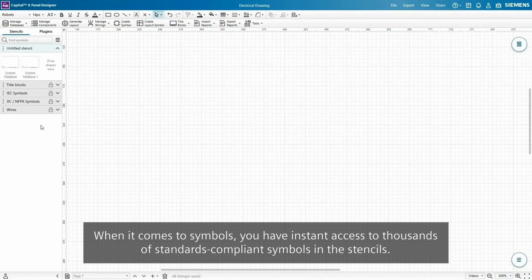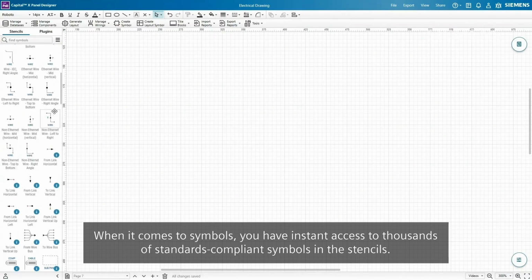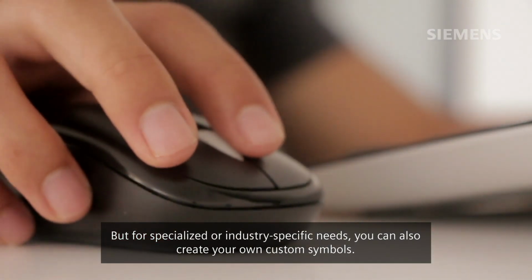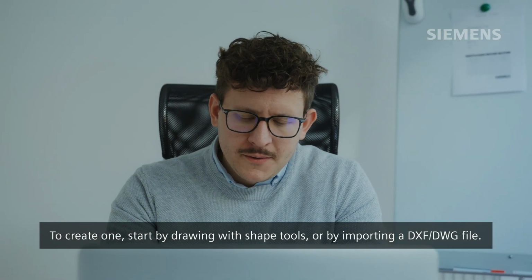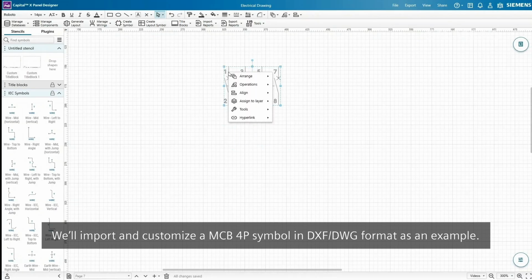When it comes to symbols, you have instant access to thousands of standards-compliant symbols in the stencils, but for specialized or industry-specific needs, you can also create your own custom symbols. To create one, start by drawing with shape tools or by importing a DXF DWG file. We'll import and customize a MCB4P symbol in DXF DWG format as an example.